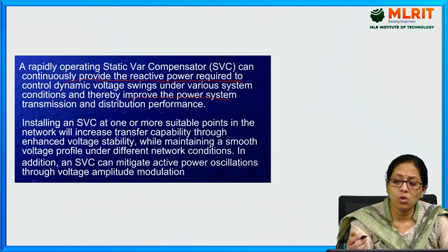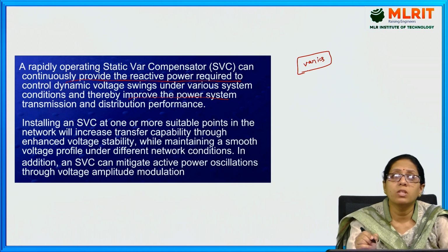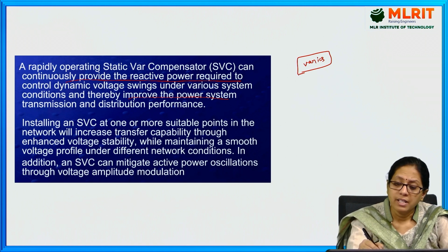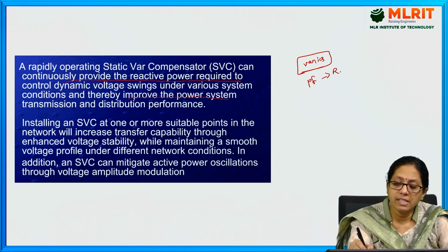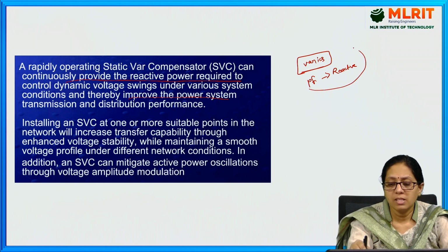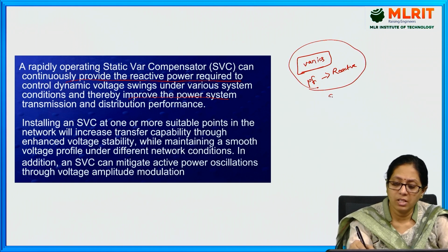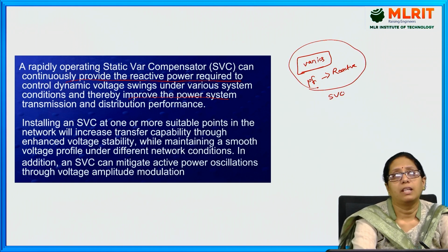The voltage also varies. Because of this variable voltage, harmonics will be created, and these harmonics will affect the power factor and will increase the reactive power. So in order to compensate all these things, we will be using the SVC technique.